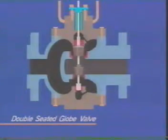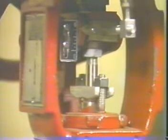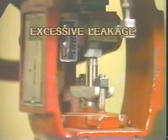As you know, secondary valve trim consists of the stuffing box components. These components prevent leakage of the process fluid past the surface of the moving valve stem. The importance of selecting an appropriate design for a specific application cannot be overemphasized. That's because excessive leakage can result in increased operating costs for a process.